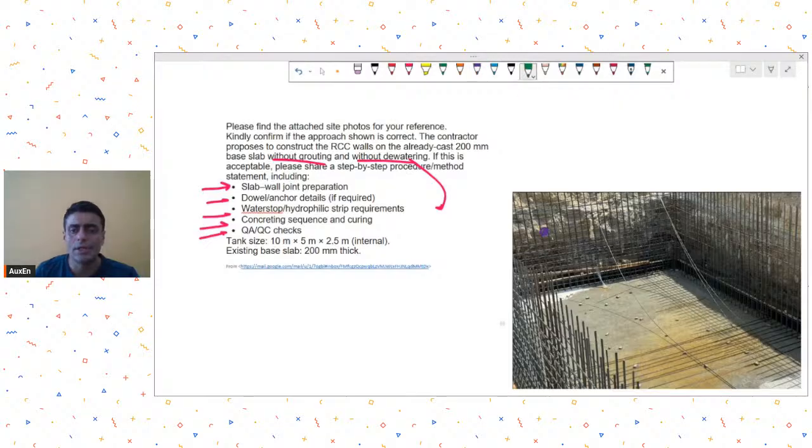You could additionally provide nipples over here. Nipple means small steel pipes that are inserted in this wall before concreting. At various locations you can have nipples, so that after concreting, if there is any issue of water leakage, those nipple locations can be used for grouting later on to take care of the water seepages. Okay, so I think these things can be managed.